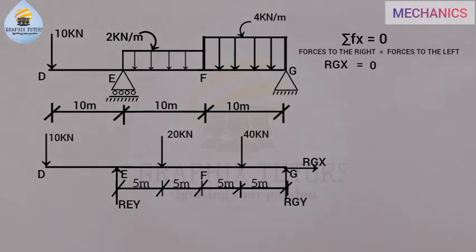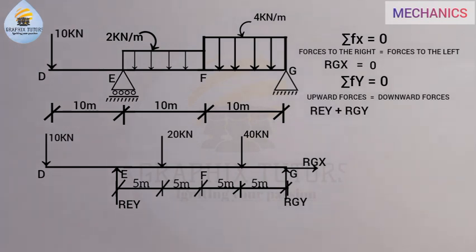Similarly, the second condition for equilibrium is the summation of V equals 0. That means summation of the vertical components. You know, a vertical component can either be upward or downward force, right? Or you say summation of Fy is equal to 0. What it means is that all upward force must be equal to downward force. That is what it means. Now, if you look at the system here, we have upward forces, which are just REY and RGY, right? These are the two forces facing upward. Now, the other ones are downward forces, which are the 10, 20, and 40.